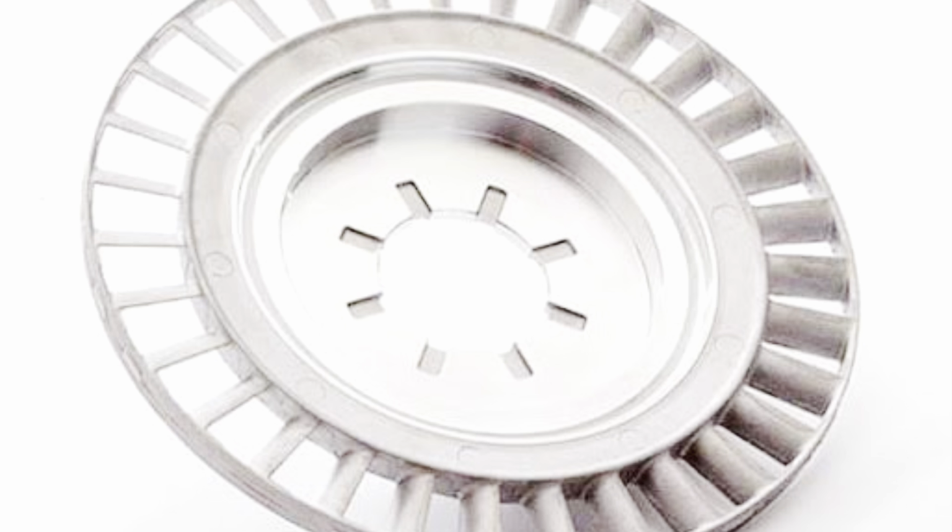With the stator stopped, the fluid is directed by the stator fins to re-enter the pump at a helping angle, providing a torque increase. As the speed of the turbine catches up with the pump, the fluid starts hitting the stator blades on the backside, causing the stator to turn in the same direction as the pump and turbine. As the speed increases, all three elements begin to turn at approximately the same speed.